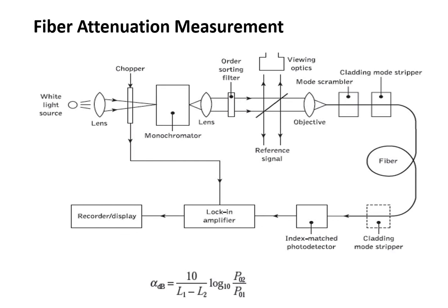The principle in the OTDR is often called the backscatter method. It is based on the measurement and analysis of the fraction of light which is reflected back within the numerical aperture of the fiber due to Rayleigh scattering. We will discuss it in the next video.